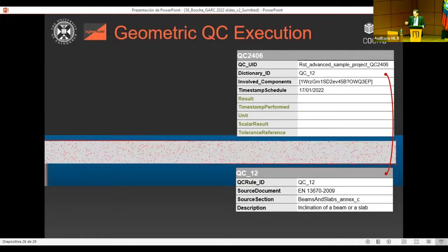Once we apply the ICP, actually I realized the pictures don't have the as-built pose. They just show the design pose. But once you apply the method, in that case, you get a deviation, measured in meters, which is higher than the tolerance for that particular context. And therefore, there is a fail.